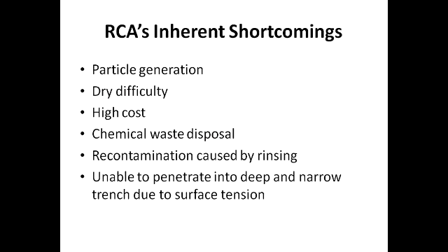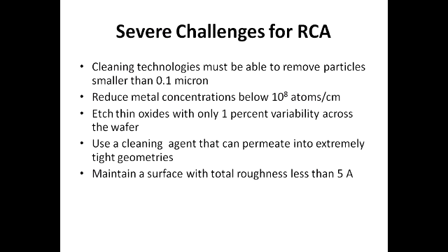Despite modification and improvement, RCA has inherent shortcomings: particle generation, drying difficulty, high cost, chemical waste disposal, and recontamination caused by rinsing. Most importantly, it's unable to penetrate into deep and narrow trenches due to surface tension. And new technology devices also challenge RCA.